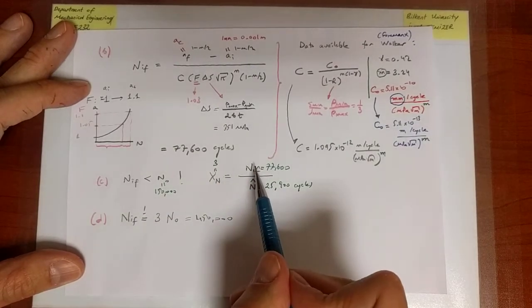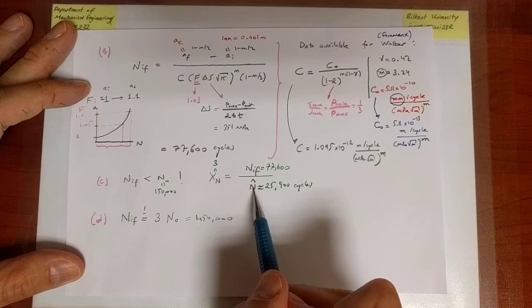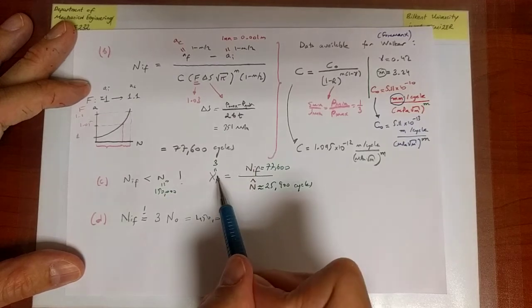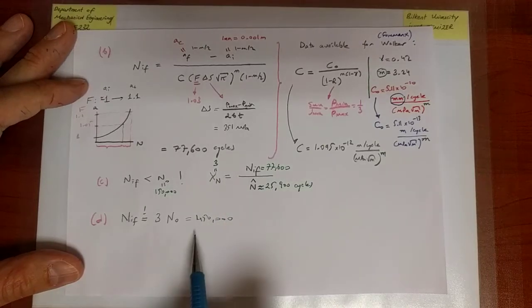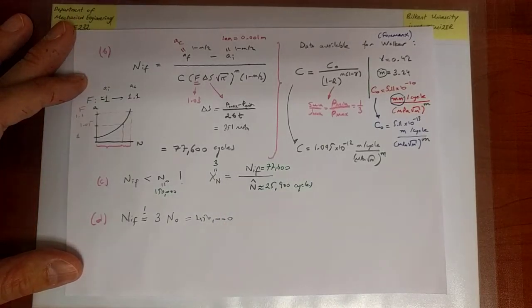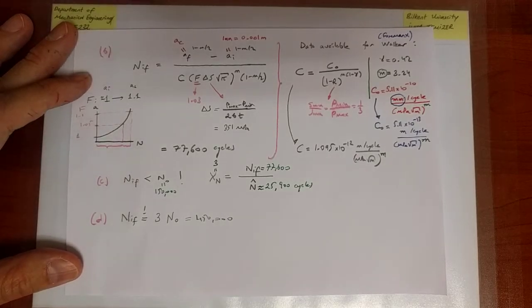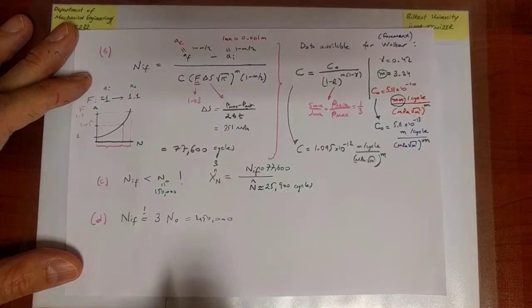Okay, so I'm trying to determine this. This is now 150,000. It's not service anymore. It's my target. This is the safety factor, and therefore 450,000 is my goal. Okay. So now the question is, what is the minimum largest crack I should find, or conversely, what should be my minimum detectable crack size so that I don't have to worry about failure.